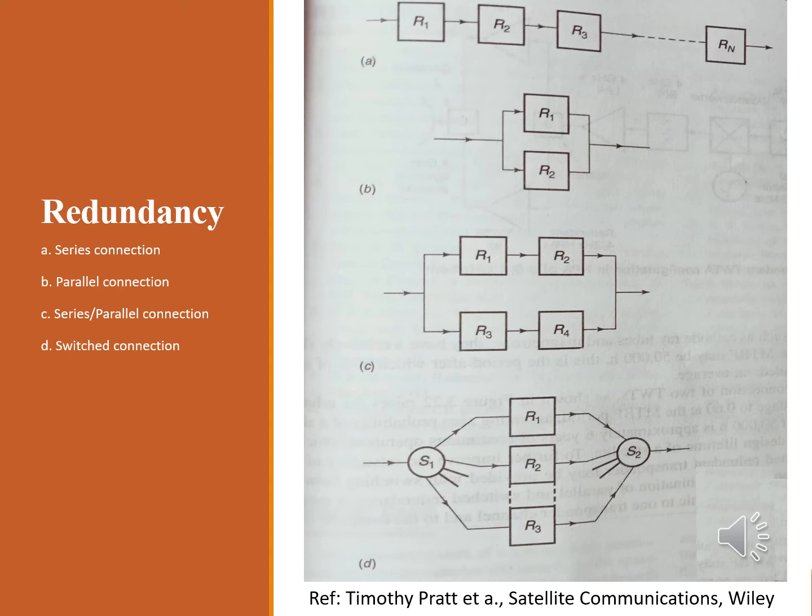The equations shown in the previous slide allow us to calculate the reliability of a given device when we know its mean time before failure. In a satellite, many devices are used, each with a different mean time before failure, and failure of one device may cause catastrophic failure of a complete subsystem. If we incorporate redundant devices, the subsystem can continue to function correctly. We can define three different situations for which we want to compute subsystem reliability.